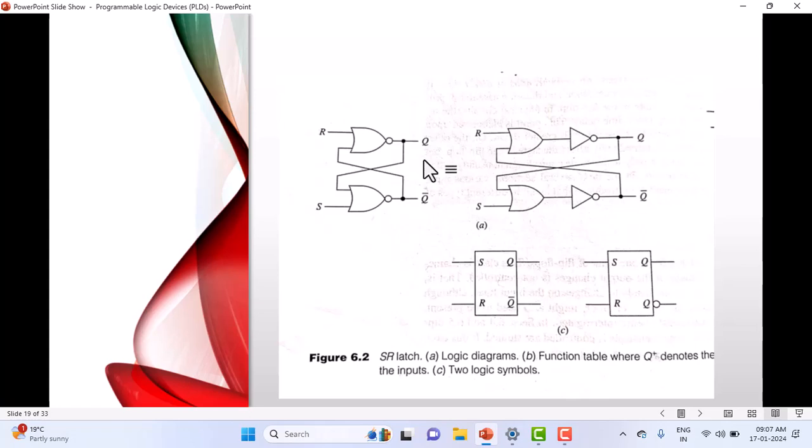In the beginning, when we are starting to find the mapping of 0 and 1, should we always start from the lower gate? Need not be. You need not start with the lower gate, but for simplicity, I have started with the lower gate. You can also start with the upper gate. But what is important here is, don't look at only one particular state and conclude that the output itself is that state. You would always see for 2-3 cycles.